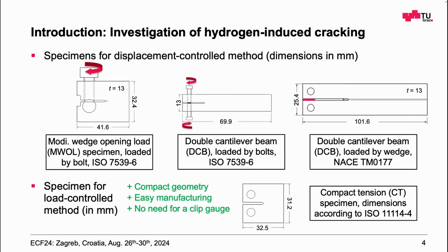The problem here is only that if you insert a wedge in such a small sample, you do not know what the exact contact force is, because you also generate some plastic deformation at the contact surface. And the actual contact force is necessary to calculate the stress intensity at the crack tip, which you need.